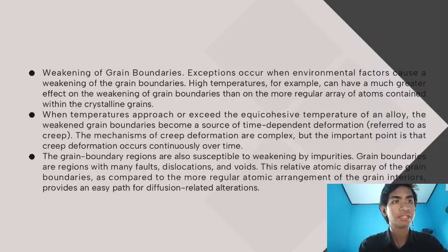Above the equicohesive temperature, coarse grain specimens also exhibit greater strength than fine grain specimens because of the lower grain boundary surface area. Thus, larger grain size may be desirable in alloys for creep-resistant applications. This also is why some high-temperature alloys are solidified into a single crystal.